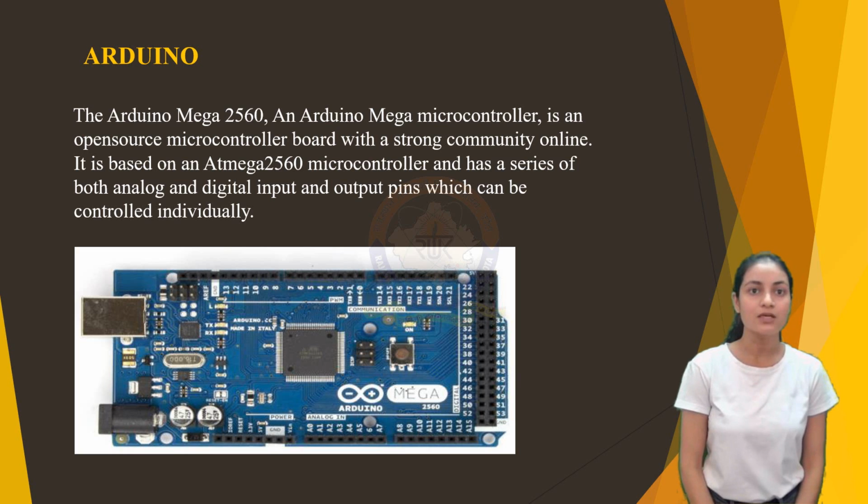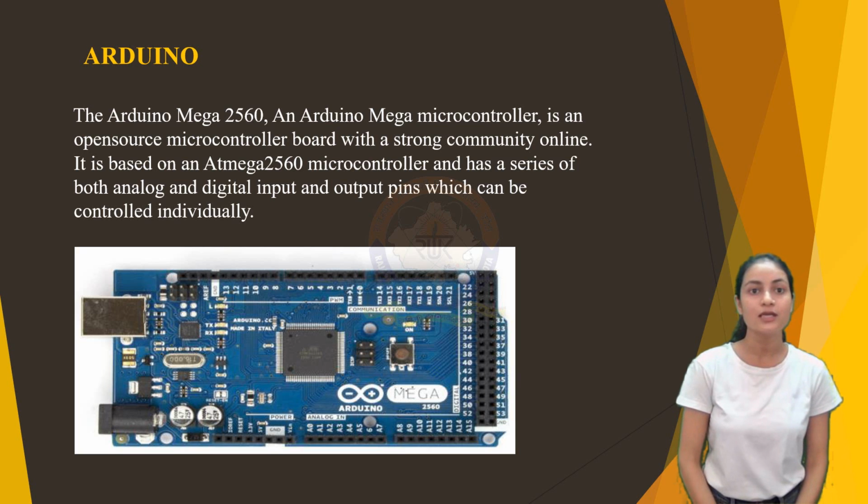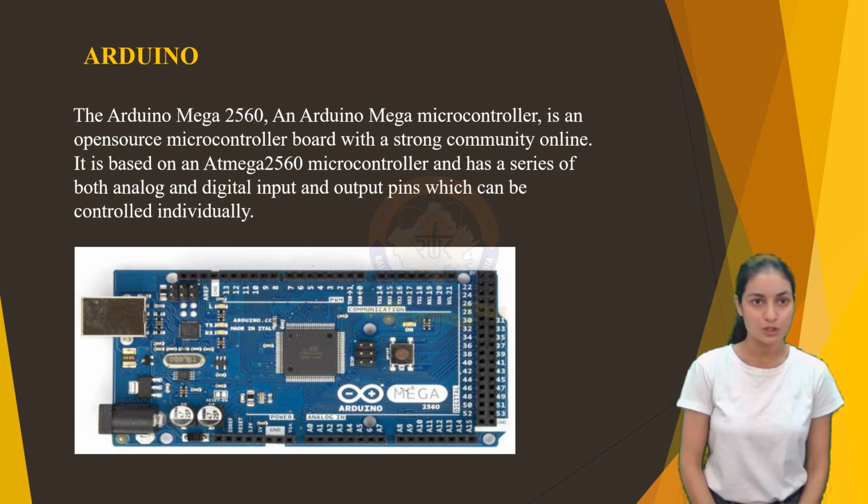It is possible to power devices and sensors through the Arduino, which is powered from either USB or an external power source. The Mega model is chosen based on its increased number of input-output pins, 16 analog and 54 digital, and also that there is an extended 4K byte of permanent local storage of type electrically erasable programmable read-only memory available on the board. These properties are key characteristics for this project because the Arduino is the central unit.